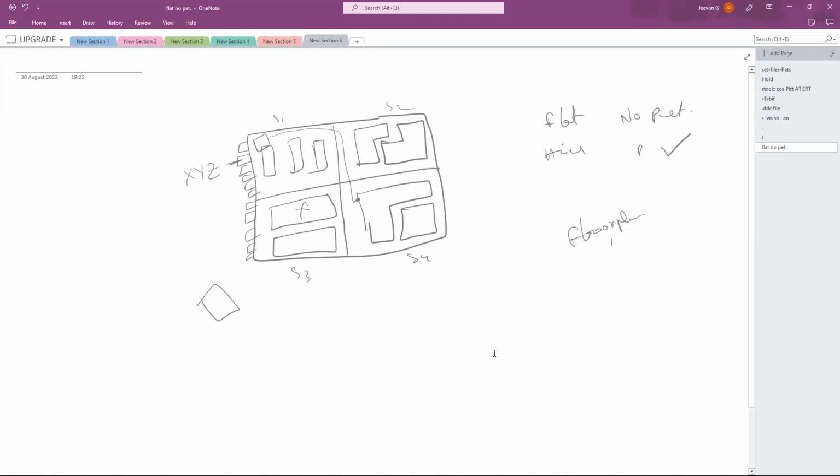So if you perform your floor plan, now you have some floor plan output, right? What is the format of this particular output? It is called .def. Whatever stage you performed in the PD flow, the output is in .def format. Usually we say just give me the DB, meaning database, in normal usage, but the format is a .def file.